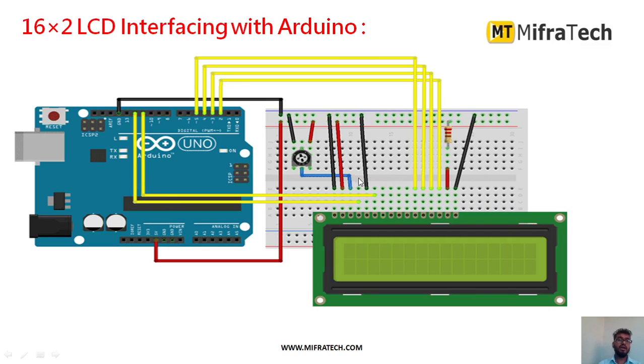So now we'll see how to interface this 16x2 LCD display to the Arduino Uno. It mainly has 16 pins. All the VCC and ground, of both the backlight and the front, we have to connect VCC to 5 volts of Arduino Uno, and ground normally connects to ground.